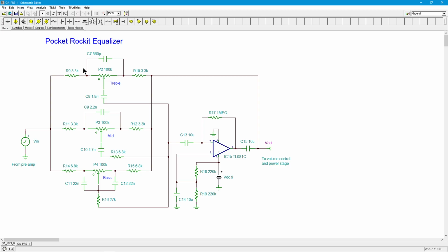Now you have a fractional gain. So just to keep it real simple, if this was 1K, this was a 10K, and this was a 1K, again with no capacitors, at the extreme over here you'd have 10K and a 1K, or 11K over 1K, for a gain of 11. If you come over here, you'd have the 1K, 10 plus 1 is 11, so you'd have a gain of 1/11.